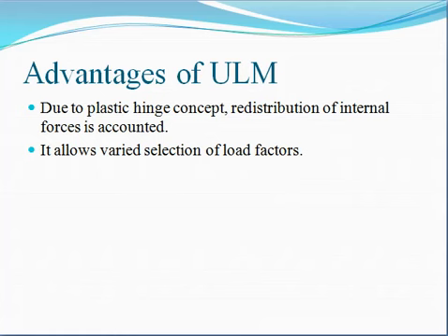So there is an imbalance between the different points within the section for the internal force. So this plastic hinge concept means these plastic hinges transfer the extra load at the point where the internal forces are more to another point where the internal forces are less in order to balance the internal force within the section or throughout the section.